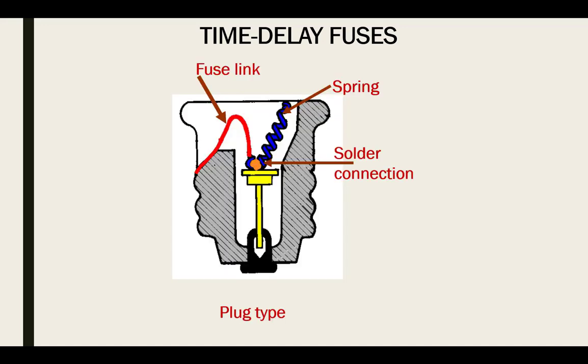Time delay fuses. In some cases, particularly when you're starting up a motor, there's such an inrush current. When the motor's first starting up, it takes more current at first than it does when it's up and running. So if I have a fuse that blows under that current, it would just blow immediately. A time delay gives the fuse time. It won't blow immediately.